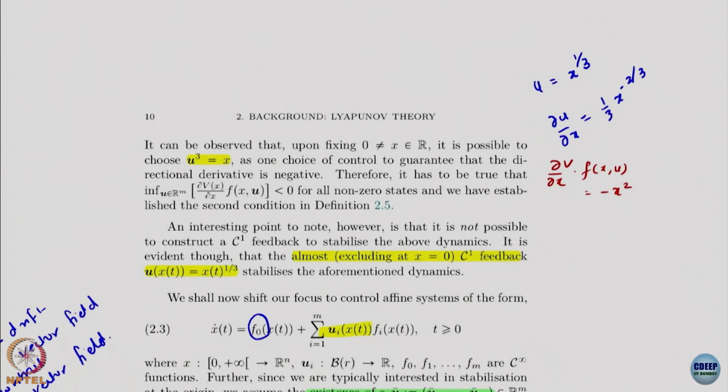And the origin is actually an important point for us because that is where we want to go. It is not outside the domain, where we would not care where it goes. So there is a certain weakness in this control: it will behave poorly when you get close to the origin, doing funny things, very fast changes, as you get closer to your equilibrium.